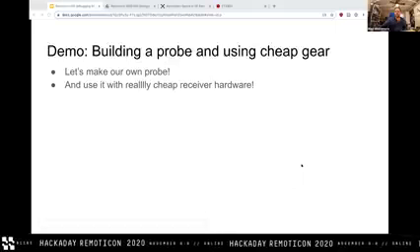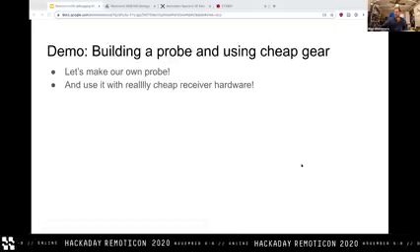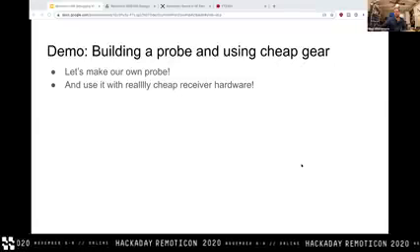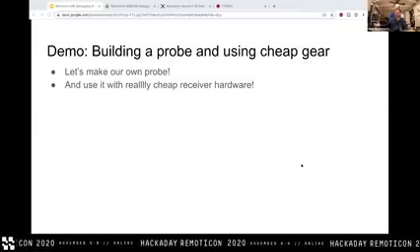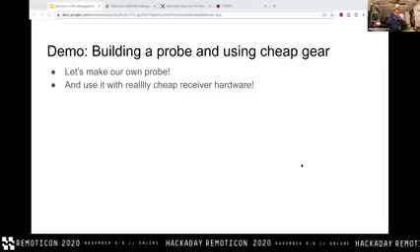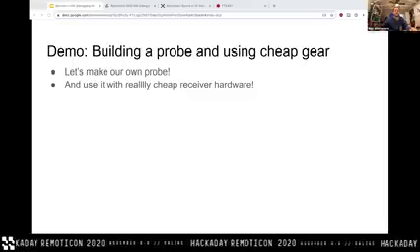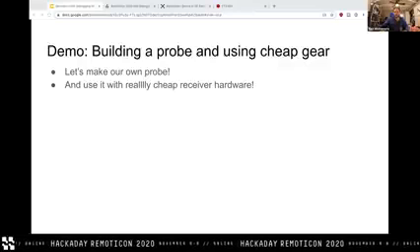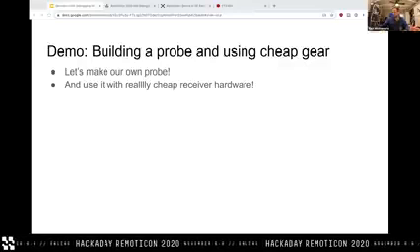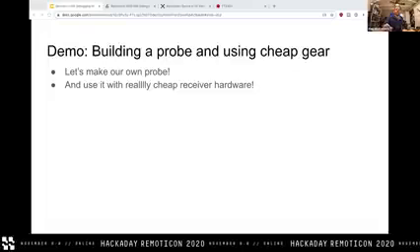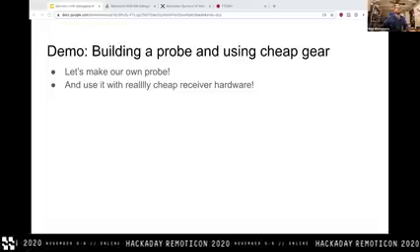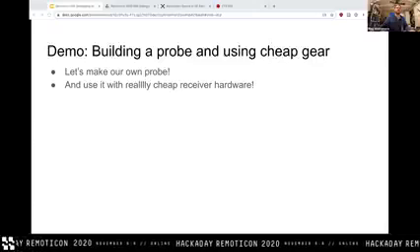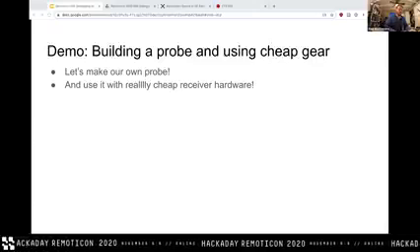So yeah, basically the outcome here is when you've got a signal that you know what you're looking for, you want to use something like this really tiny probe to find exactly which pin it is. So let's go ahead now that we have a probe taken care of and we've got all of our RF stuff set up. Let's go ahead now and actually fire up the RF toolchain, or sorry, the SDR toolchain, and see about doing this the cheap way.